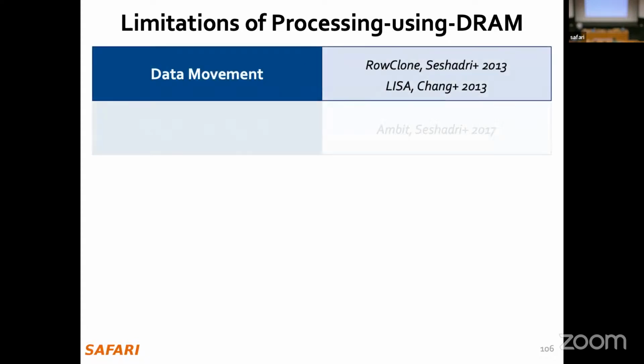So it's quite common, actually, if you have an embedded system, you just put a table with the most common angles that you are going to use inside your memory, your microprocessor, and for other angles you just interpolate based on that, and then you just use that as an approximation.